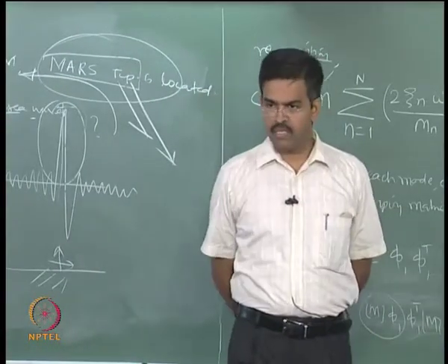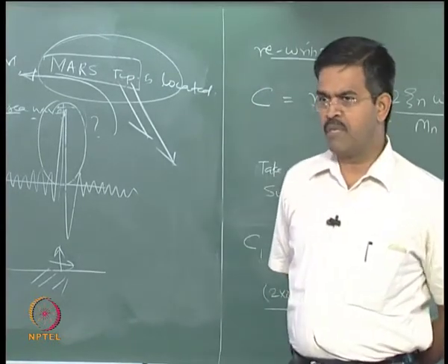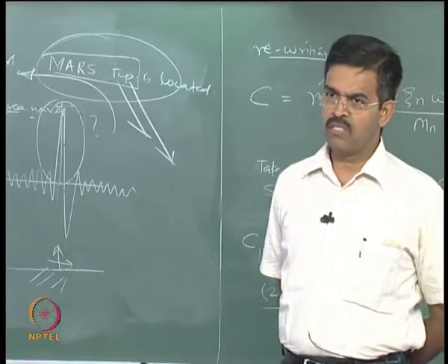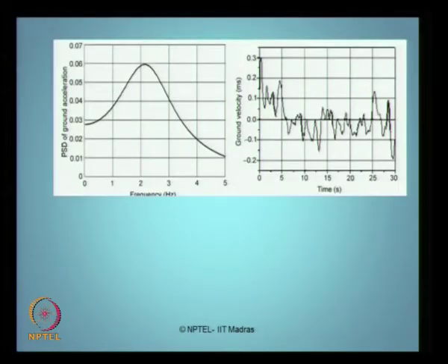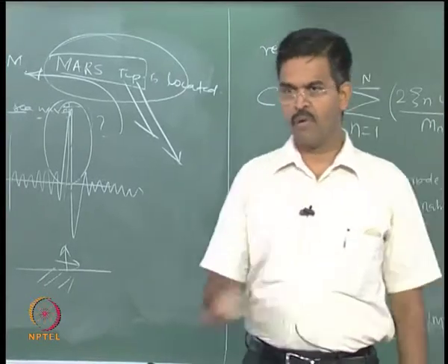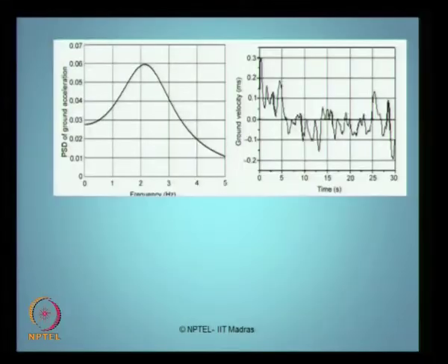Once delta T changes, of course K and M get updated, and C also gets updated. In addition, the buoyancy force changes and therefore f of t also changes. So I get the f of t right hand side vector as a sum of distinctly high sea waves generated artificially using the modified Pierson-Moskowitz spectrum plus delta T arising from the artificially generated Kanai-Tajimi power spectrum in horizontal and vertical axis both. So I get a superposition of both these forces.